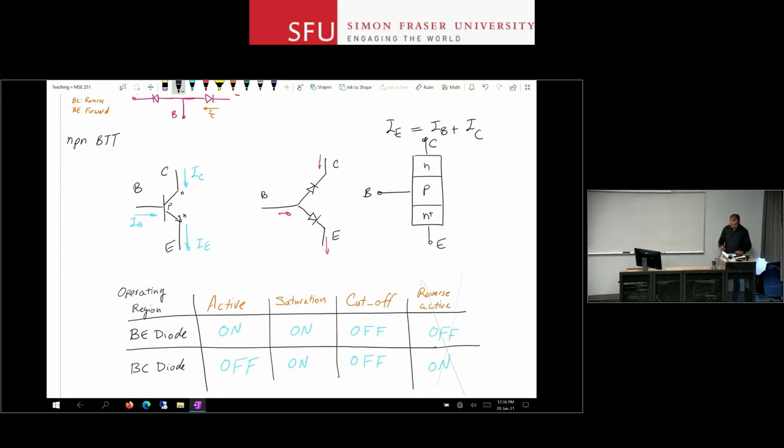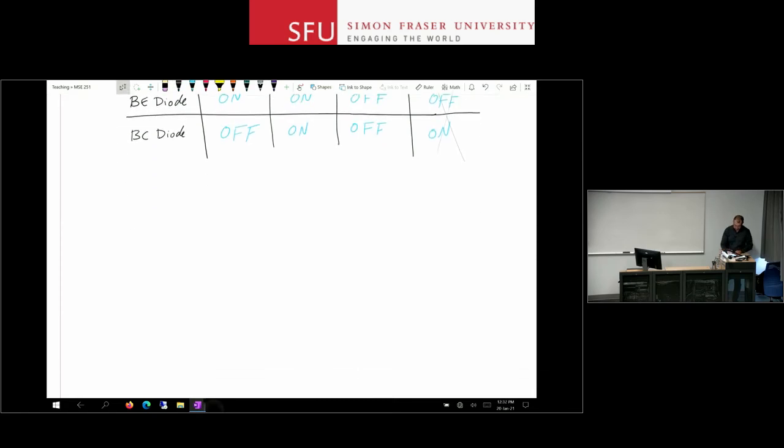And in this case, for us, the stimuli are voltages and currents, right? So I'm going to use voltage sources here. I'm going to keep the device in the active region. The cutoff region is the easiest of all. You have 2 diodes that are both off, you replace them with 2 open circuits, and you'll be done. The saturation region is a bit more involved, but still, 2 diodes that are on, and you can solve the circuit easily. The active region is the new one, the area that we probably need a little bit more attention.